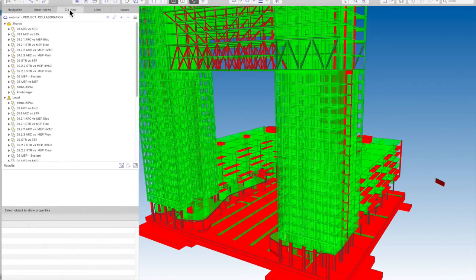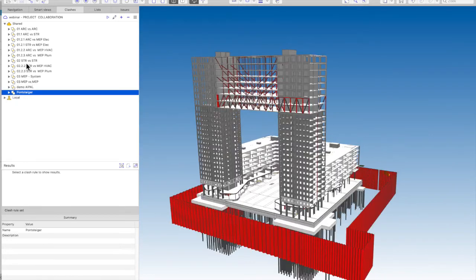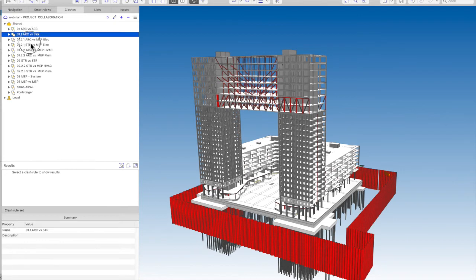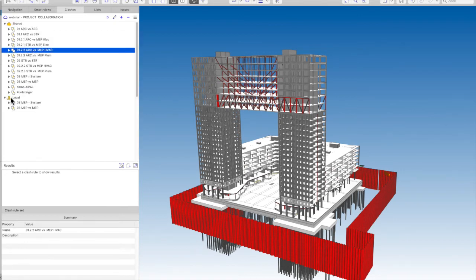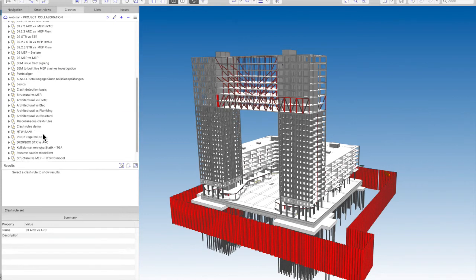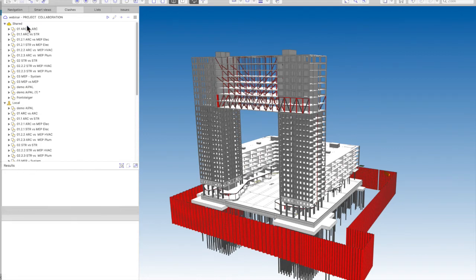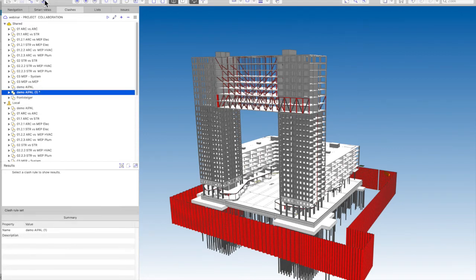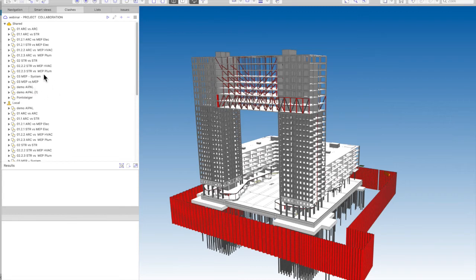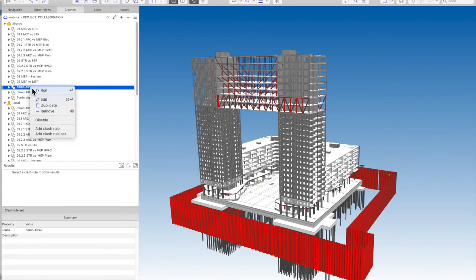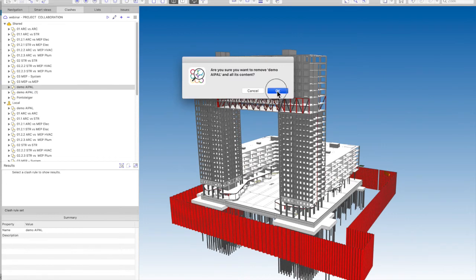I was asked to show also a little bit about clash detection. I mean, that's one of these BIM coordination things, that it is a geometrical clash. There are other more advanced checks. We do geometrical clash here, and we can also share these questionnaires with my team in the cloud. I can prepare everything locally on my machine here, but when there is a need, I can just drag and drop it to my cloud, share it, and every team member of my BIM coordination platform will have the same up-to-date information even on these questionnaires.